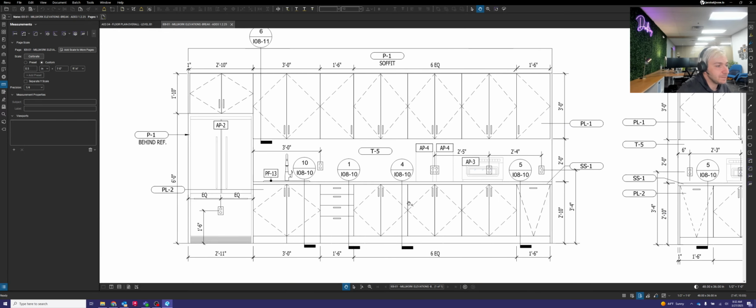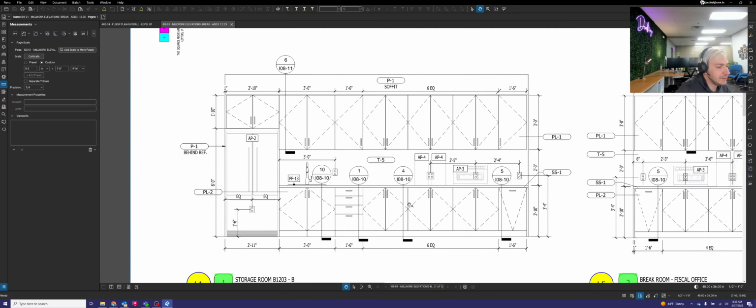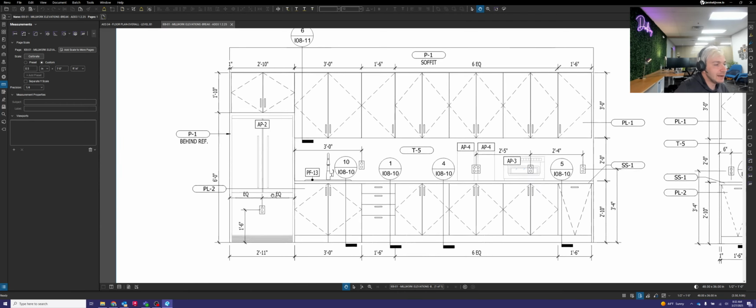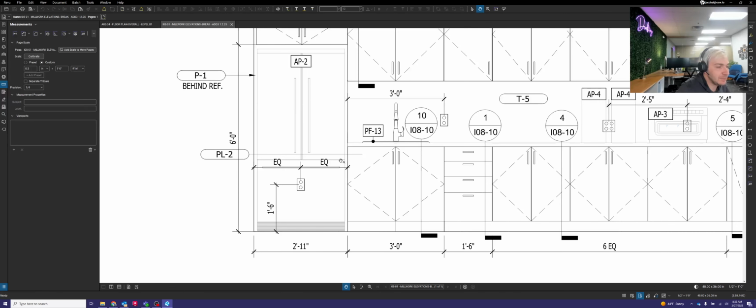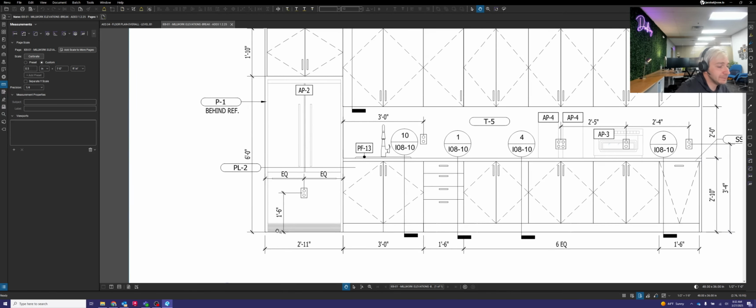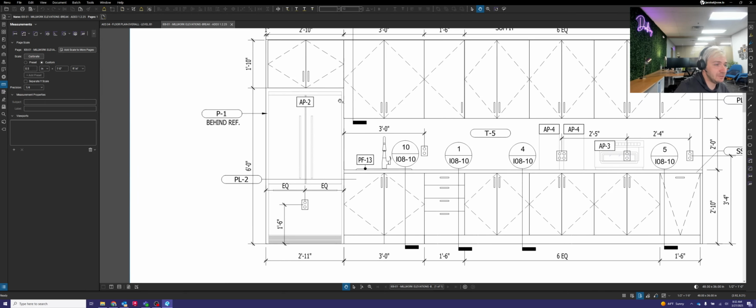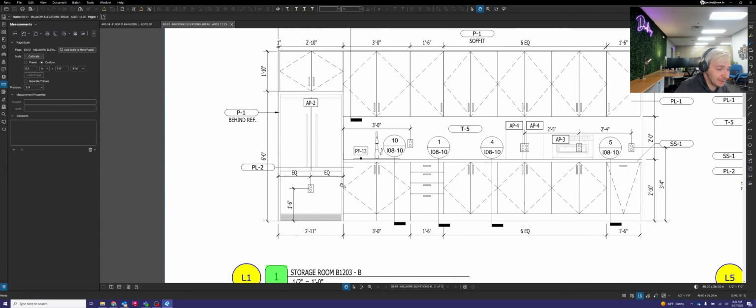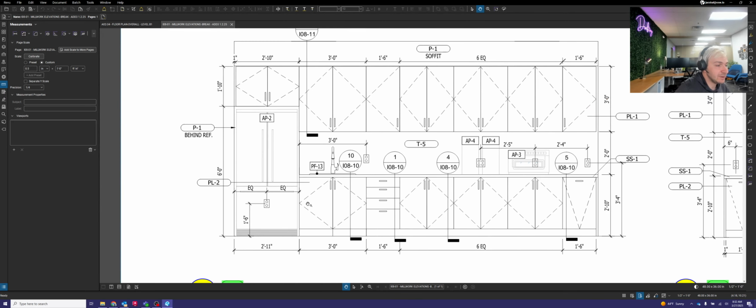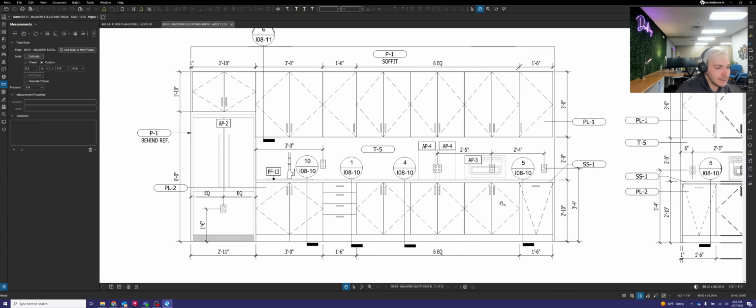Let's go back here. Let's see, anything else worth noting? Well, I can tell you right now that because there is a refrigerator sitting in this opening, we're going to have to make sure that we label a finished end on this cabinet here and a finished end on this cabinet here, because you will be able to see a portion of the side of these cabinets where the refrigerator sits. So we're going to label those as finished ends when we get to drawing these. Just make note of that as well. All right.